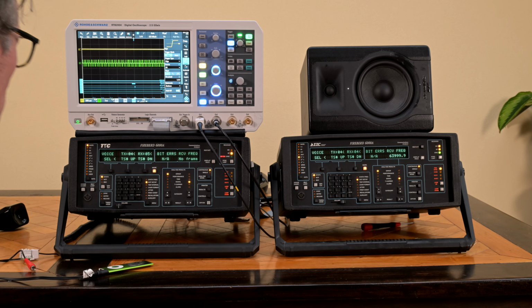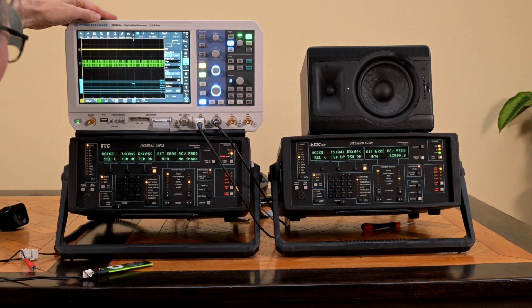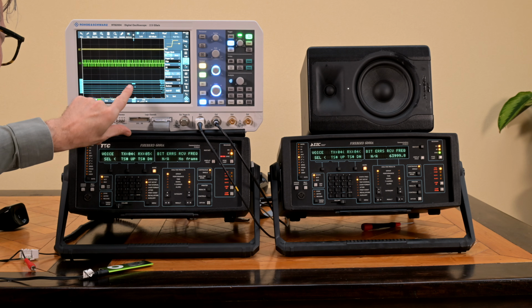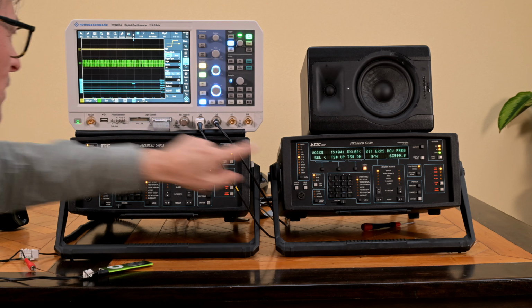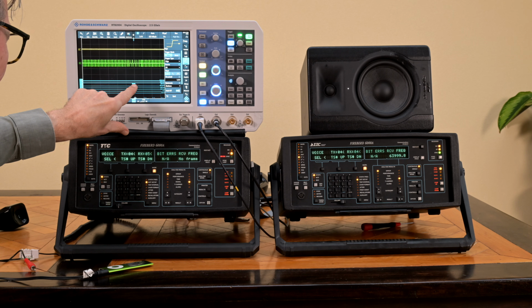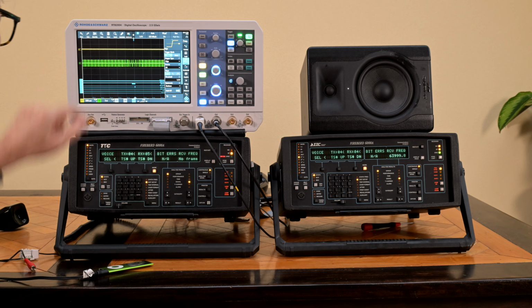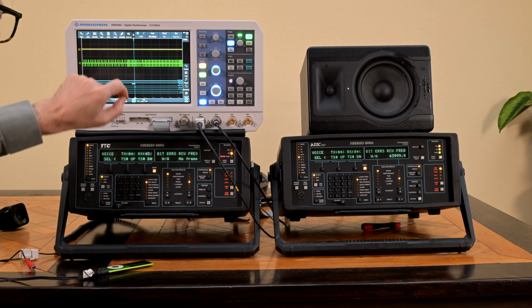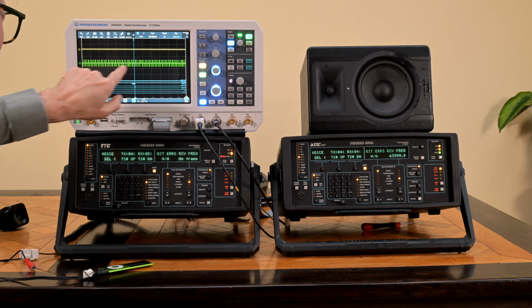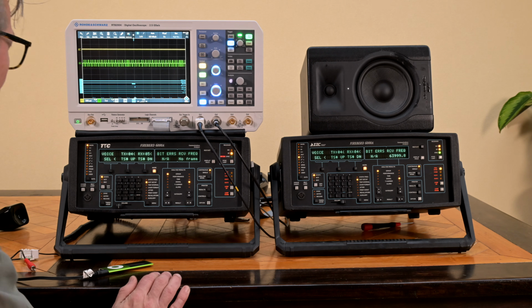Now, another nice thing is that we can actually see the time slots when data is being sent over. Because if we look carefully here on the oscilloscope, with one voice channel in, we actually see that this voice channel is right over here in the data, and actually that is the generator clock. So the clock signal is only generated down there, and we can also see in the data that there is music playing right over here.